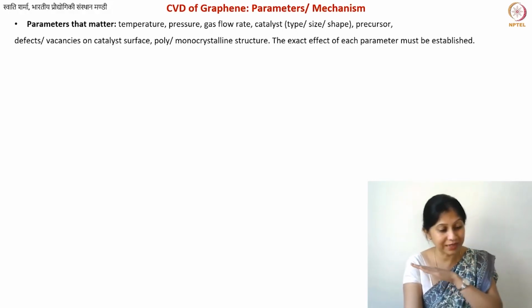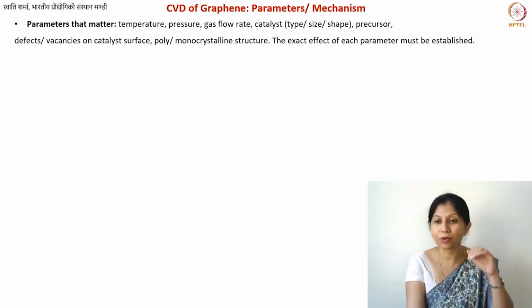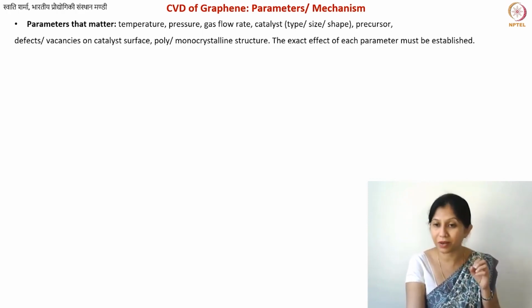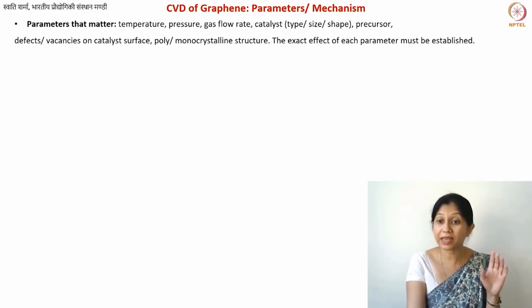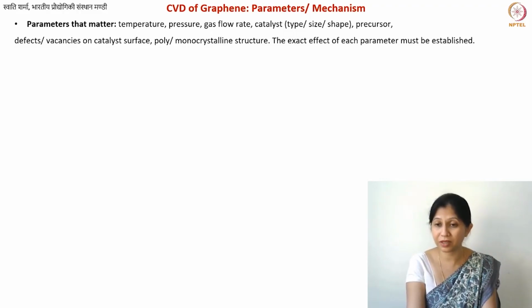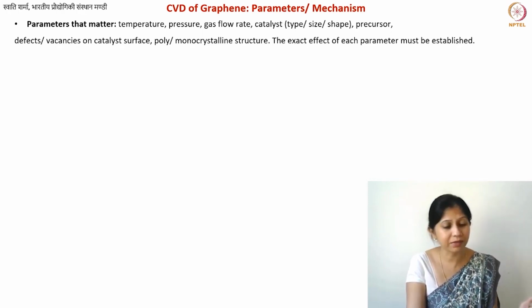Sometimes you just want one single extremely thin film. You don't want multiple nucleation points. And the uniformity of the film in the single layer is more important to you, especially in the case of graphene. In that case, you can use single crystal type substrates, or you can use polycrystal, depending upon what kind of film that you're looking for, and what is your ultimate application.